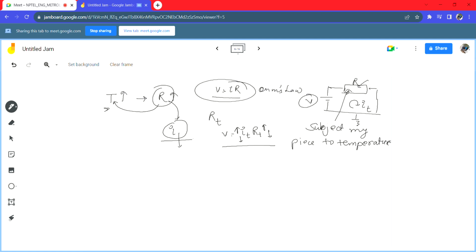So the line of command here was: we had to find temperature changes. With the temperature changes there was a change in resistance, and with the change in resistance the current I started to change in the loop, and by identifying this I we actually determined the temperature T.